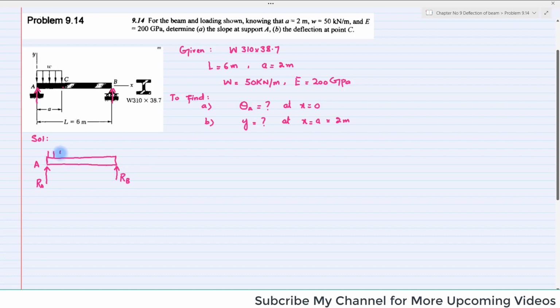There is a uniformly distributed load w, starting from point A. And this w is equal to 50 kilonewton per meter. Clear? In order to convert this uniformly distributed load into concentrated load, you know that you have to multiply w with a and it will be converted into concentrated load. Let me draw it separately quickly.